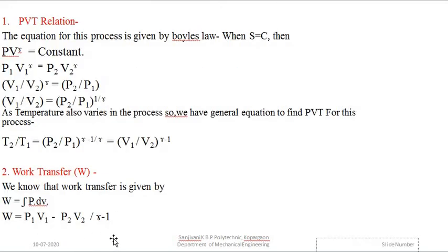We can also write this equation in terms of the general gas equation, that is P1 V1 we can write as mRT1 minus P2 V2 we can write as mRT2. So mR into T1 minus T2 divided by gamma minus 1. That relation we can also use to find out the work transfer.